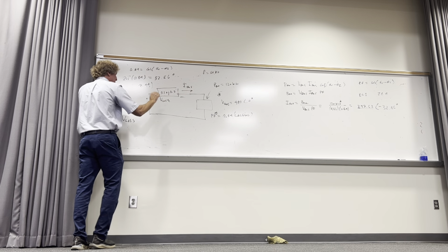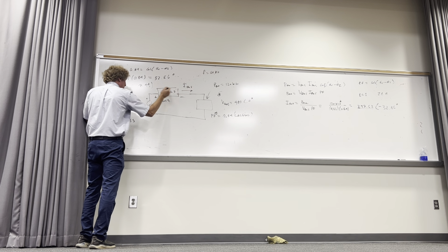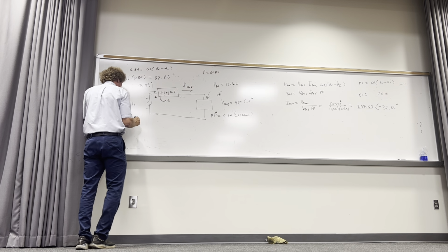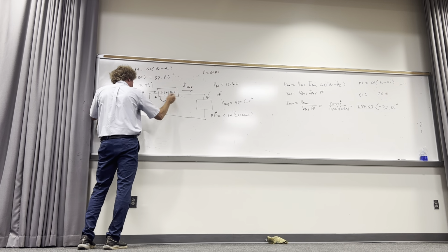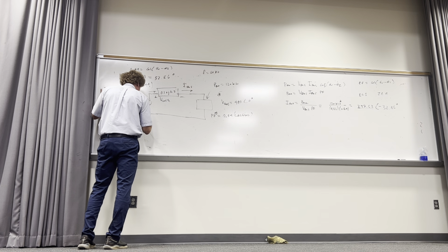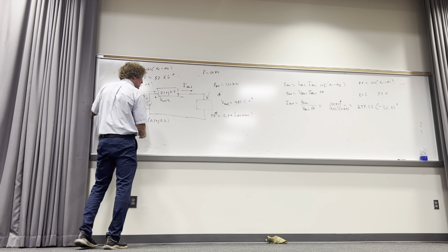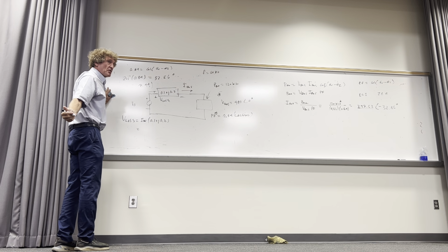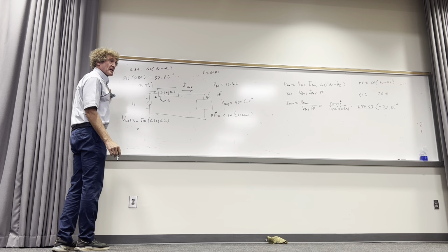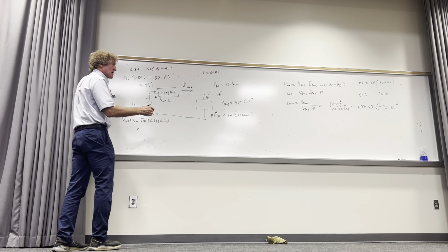Notice how I put the plus here. That means the current's going in this way, coming out that way, so plus to minus would be the orientation of that, and that means it's going to be IRMS times 0.1 plus J 0.2. IRMS, get your calculators out, make sure you don't mess these up. Here's something that people mess up. One of the numbers is going to be in rectangular, the other polar. People mess this up, and I know this.